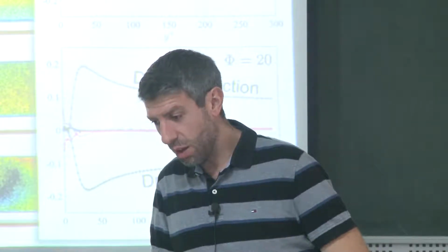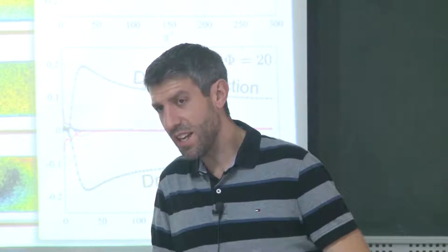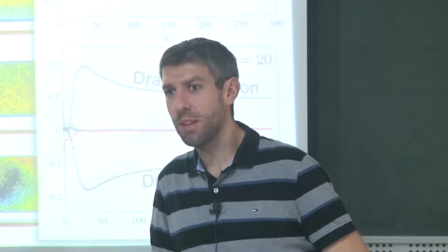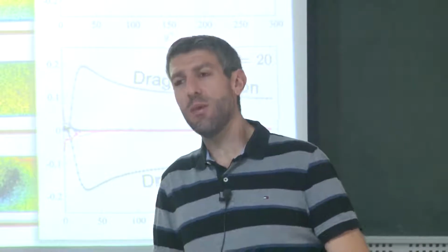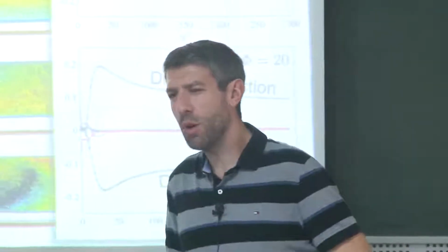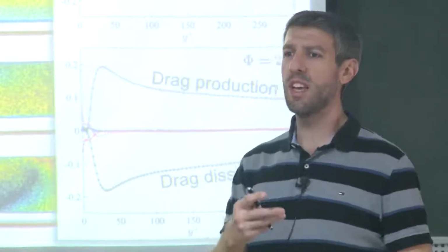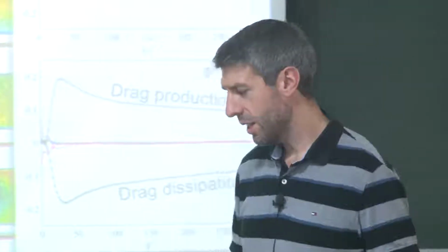The underlying assumption when you want to run an LES type of approach is this idea of cascade, of self-similarity, of being able, at least if you want to have some sort of a dynamic modeling approach, to say that your knowledge on the resolved scale is sufficient to close your model at the under-resolved scale.